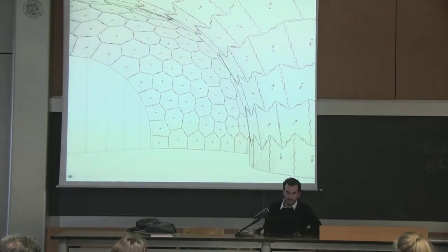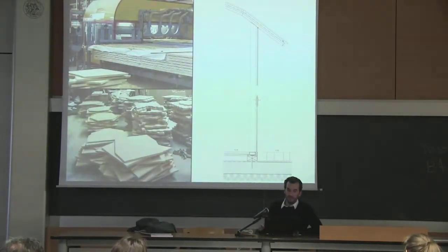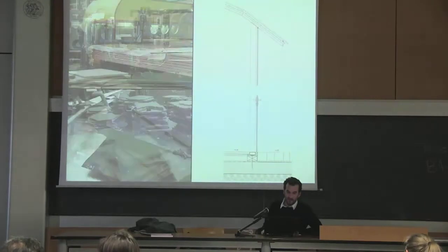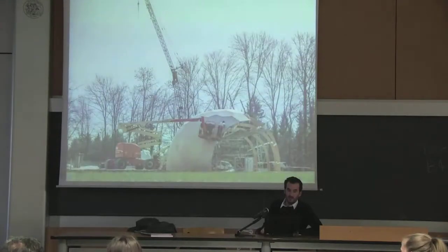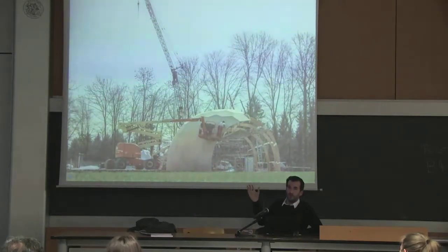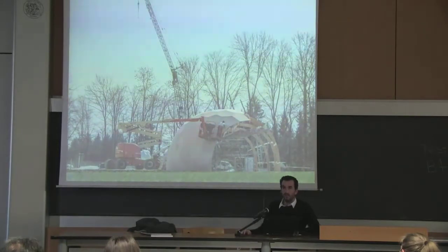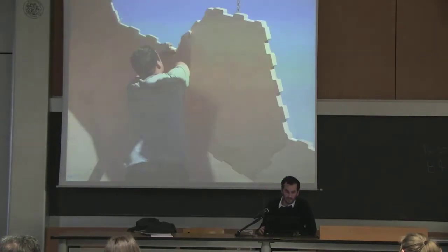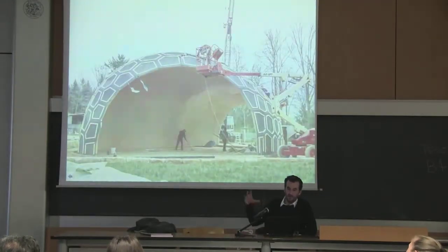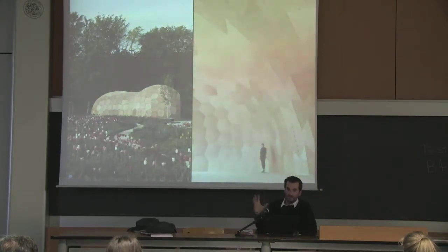That's the architectural surface. It's also interesting to note that this building was completely digitally fabricated. So it is a fully equipped building, has insulation, cladding, everything, and all that is digitally fabricated. So we have a 5-axis insulation layer, a membrane, and then the system is set up on site in a very short amount of time. It took 3 weeks to prefab the whole building, and it took 8 days to set it up on site. Because again, it is a large puzzle that can be simply erected, and then the additional layers of insulation and waterproofing are added. And finally, an external timber cladding is applied so that on the outside you have this timber appearance, but on the inside you actually see the structural plate shell.